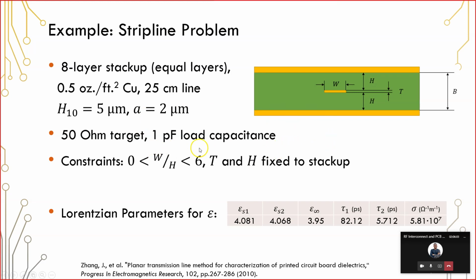What I mean by that is even if you terminate that input on a component to 50 ohms, there is still some load capacitance, and that capacitance will cause the input impedance of your receiving component to look like much less than 50 ohms at very high frequencies. So that 1 picofarad load capacitance in this example will actually create some deviation in the impedance, and we'll see what that looks like on S parameters here in just a moment.